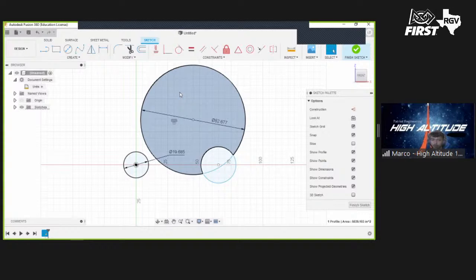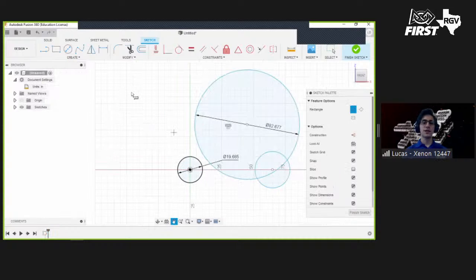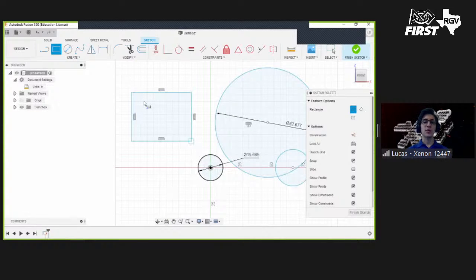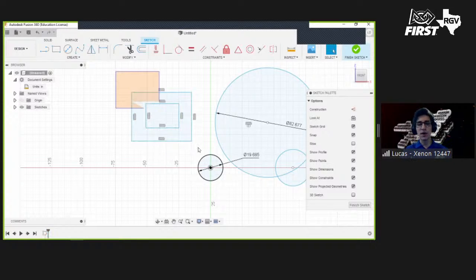Yeah. So putting a sketch within a sketch will create a new face. What do I mean by that? Well, let's make a sketch, a rectangle. Let's put a rectangle inside that rectangle. And notice, if I click this, see it automatically highlights. I created a new face. So it doesn't just highlight everything, it highlights that. And if I did want to highlight it all, then I would drag and highlight in case I needed all of it. But it's a very useful thing.